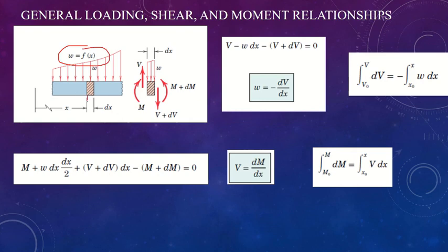Now, in order to do that, we have the shear force acting on either side of this component and a moment, that is, the couple acting on either side of the faces. We have to remember, once the convention is followed, we have to follow it through the entire calculation. Since the system is in equilibrium, the shear force acting upward and the shear force acting downward should be equal and opposite in nature. So we are going to start from the far left side.